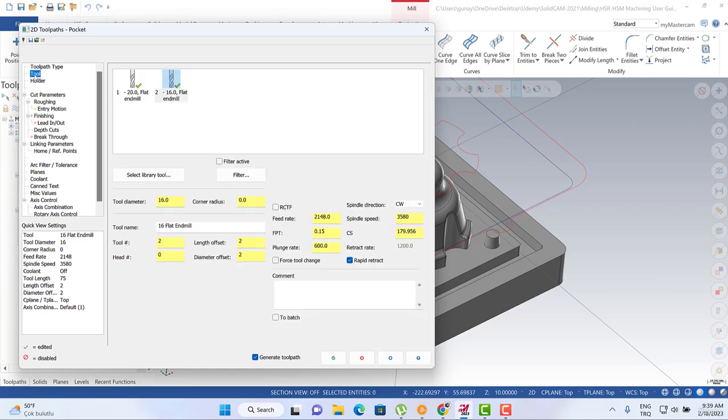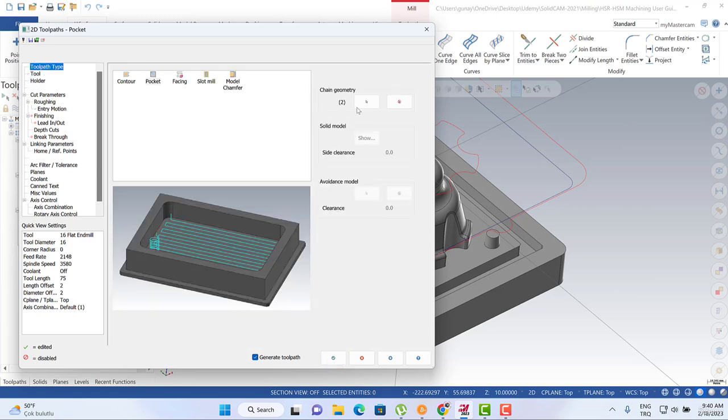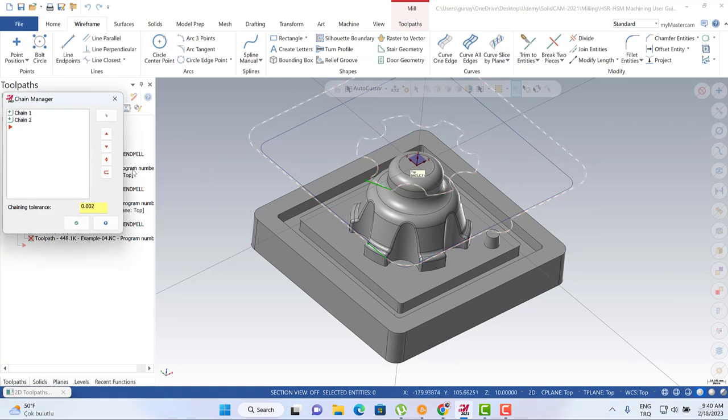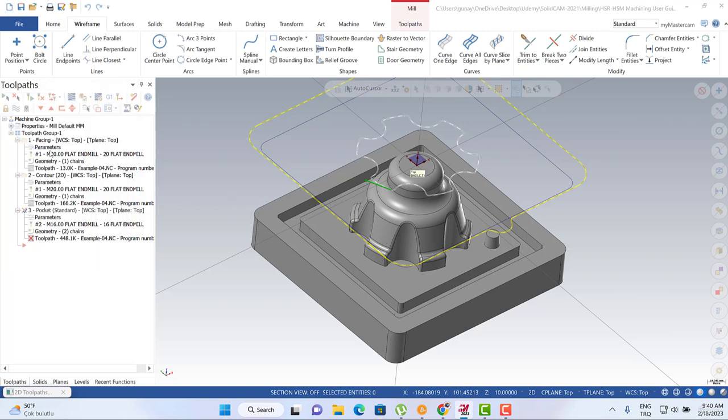When we turn to the tool properties, we're going to see this is my plunge rate. You can also organize your plunge rate. This is my feed rate, and this is my plunge feed rate. It can be like this. Okay, after that, when we click here, this toolpath is going to ask us for our entry point. So let me turn to the toolpath type and geometry, and then we can use the right mouse button and add new entities.